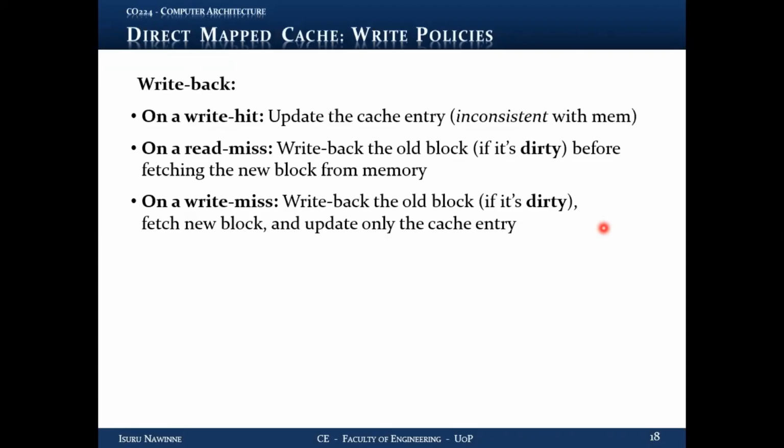Your write traffic will be significantly reduced between the cache and the memory, but your cache controller becomes more complex, right? You have to maintain a dirty bit along with the other arrays in the cache: tag, data, and valid bit arrays.